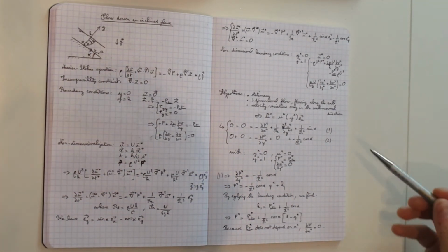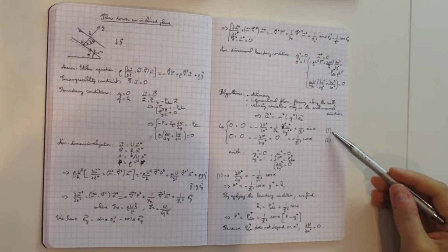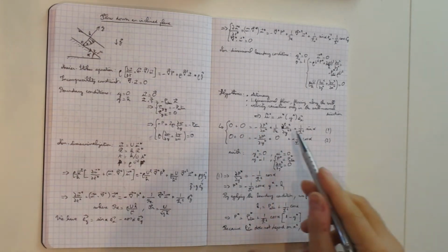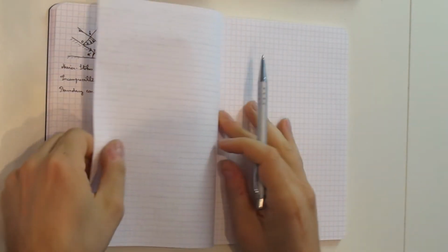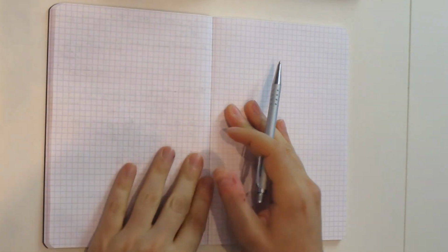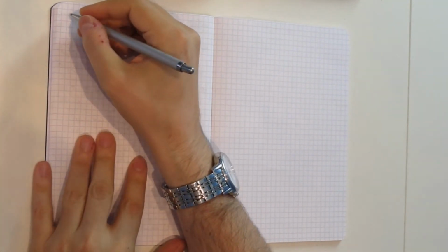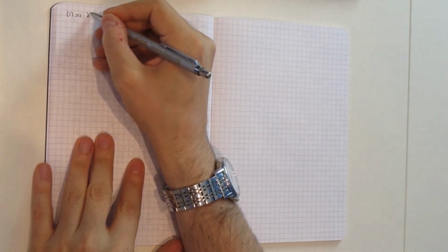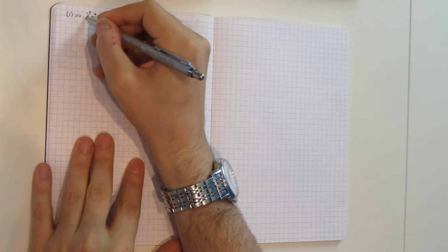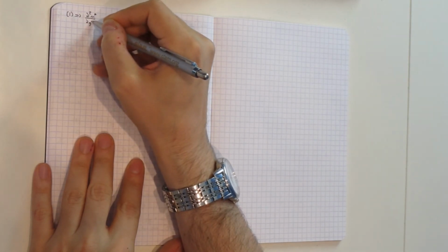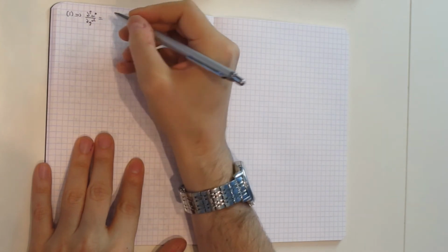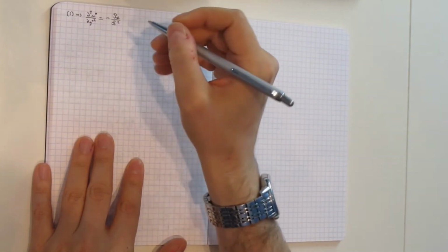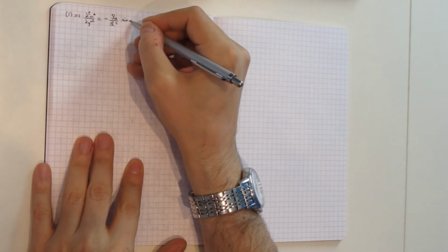So now what we are left to do is to solve equation 1, bearing in mind that this term is 0. And so we're going to solve for the velocity u star. So equation 1, now simplified in this fashion, gives us that d2u star over dy star squared is equal to minus the Reynolds number over the Froude number squared times sine alpha.